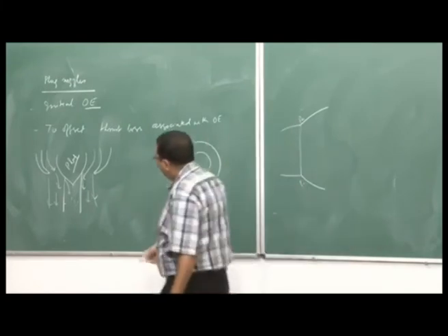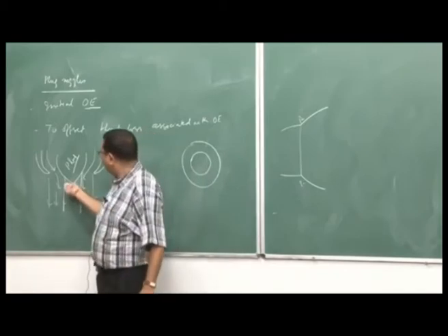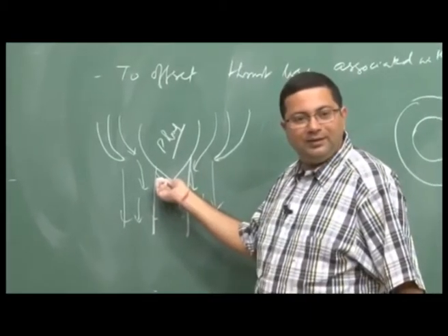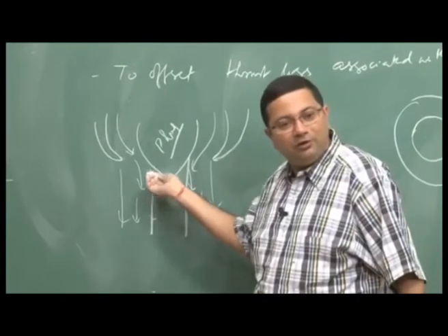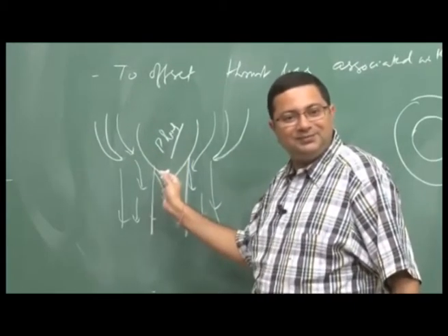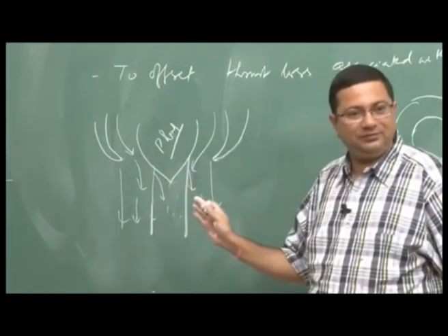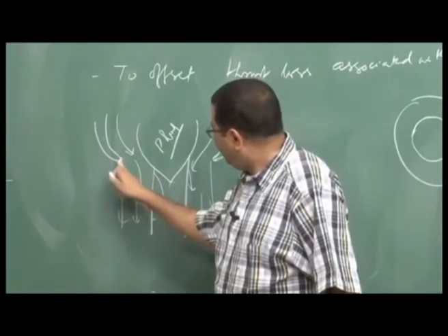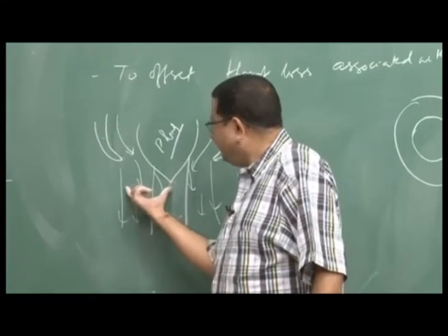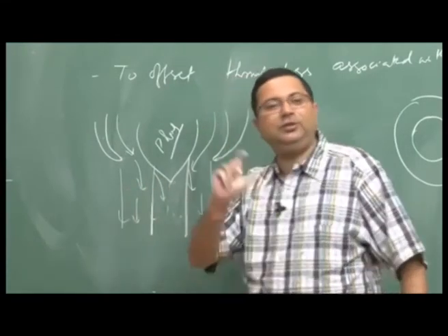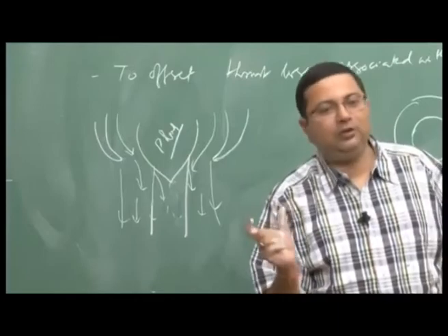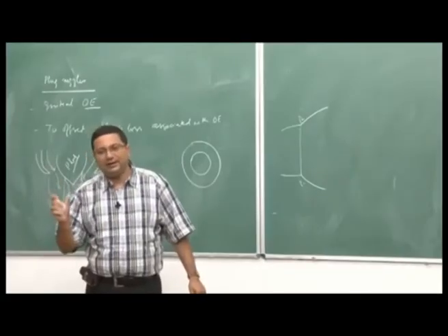First of all, whatever shock wave is there, it is generated from here, and that shock wave now can be controlled by proper designing. So, you can have a weaker shock that will reduce the losses. Secondly, the distance here will determine how much will be the reflected shock wave, and that can also be then controlled with the design.